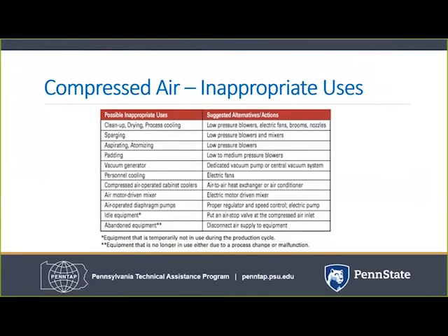Take steps to eliminate any inappropriate uses. You may want to consult with a compressed air system specialist to see if other equipment, such as blowers, mechanical, or hydraulic devices, will be more cost-effective for those applications.